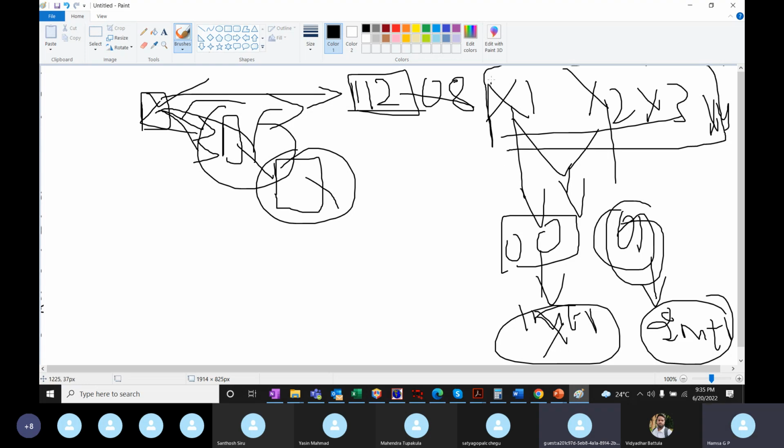This is the actual data which is present in the data field. And how many bytes of data you are going to send in this data field will be identified in the DLC, which is the data length code. And in the CAN protocol it is fixed. The standard says that you can send only 8 bytes of data in a single frame. In the data field you can send only 8 bytes of data.